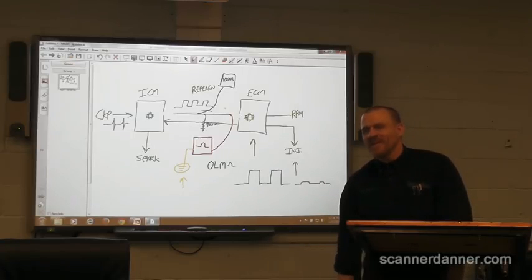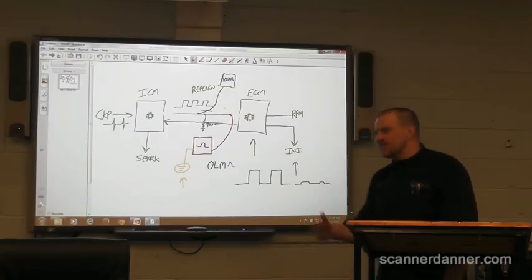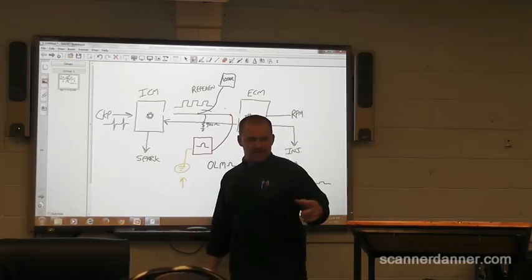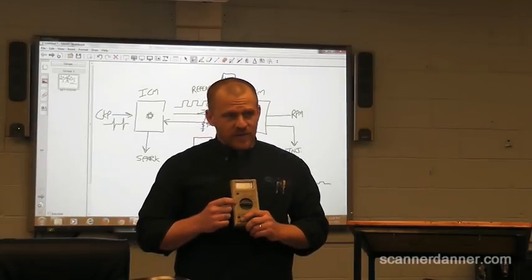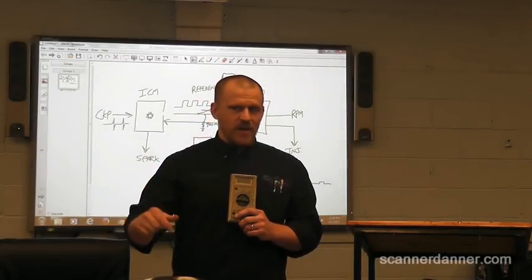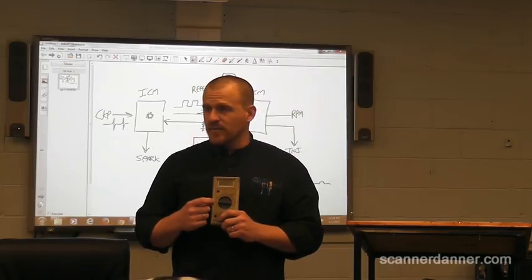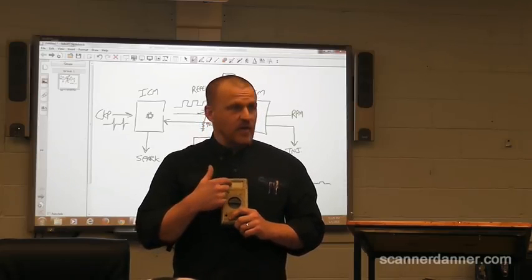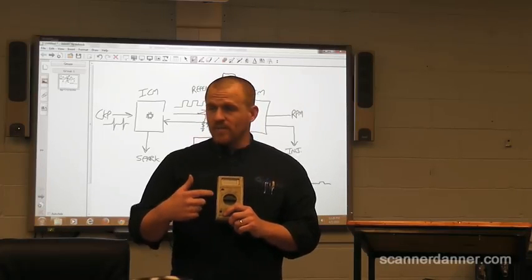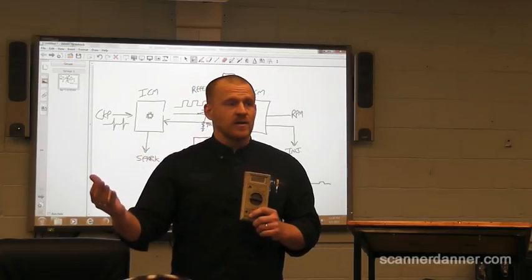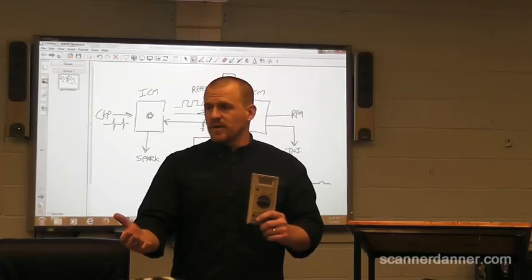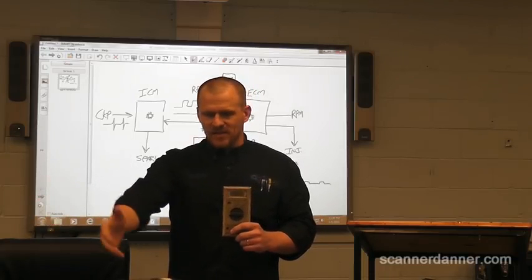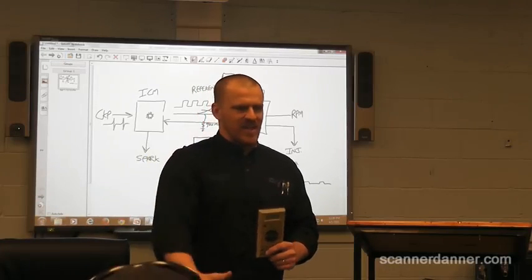Awesome. All right, but back to the resistance measurement. Do you understand, if I had done this short to ground test on this meter and started on my lowest scale, which is 200 ohms, my meter, well, there's no battery in there, would have said OL, and I would have said what? Maybe, not thinking about the wire. The wire's good. You guys with me on the statement I have in section 1, which is a foundational statement.